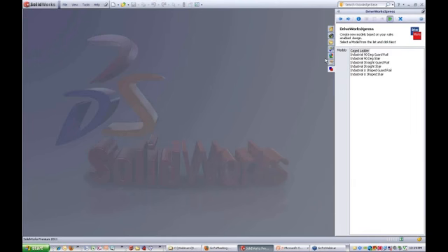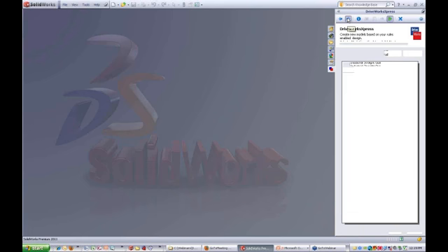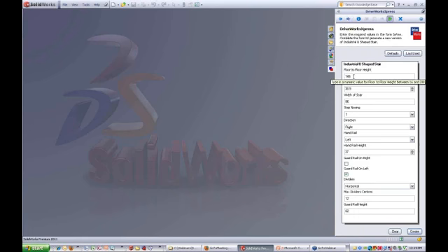We'll run it again. Another U-shaped stair. This one will put in some different data. So we'll make it show the distance between the stairs, the minimum angle this time, much narrower stairs. Step nosing, go to the left, handrail on the left, 34 height.